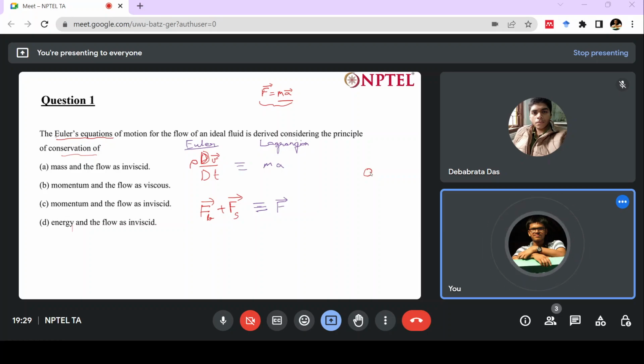After a critical Knudsen number, we can consider it to be continuum. And in that continuum, even if you select a particular point, that point will be associated with a large number of water molecules, such that continuum properties like density can be assigned to that. So what will be the body force at that particular point?